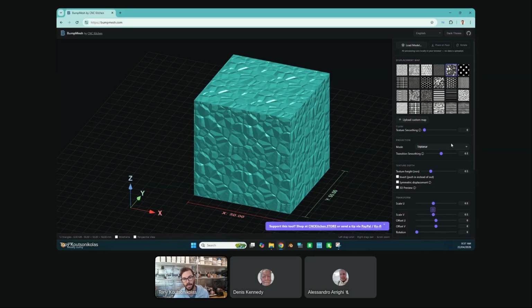And then also, of course, the aesthetics of it, which is a really big one, because when we 3D print a really smooth object, if we design a really smooth face, then a lot of the time we can get a shiny kind of appearance, and that might not be what you're looking for. Usually when you're adding a texture, you soften the way that it's reflecting light because you're making it scatter light a bit more instead of reflecting it like a mirror.